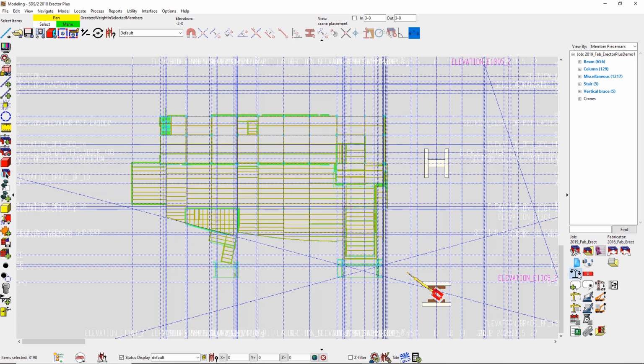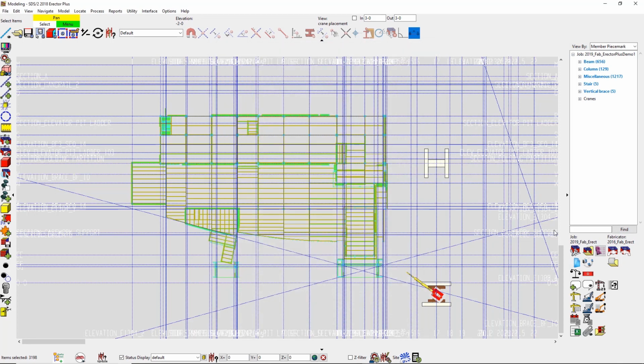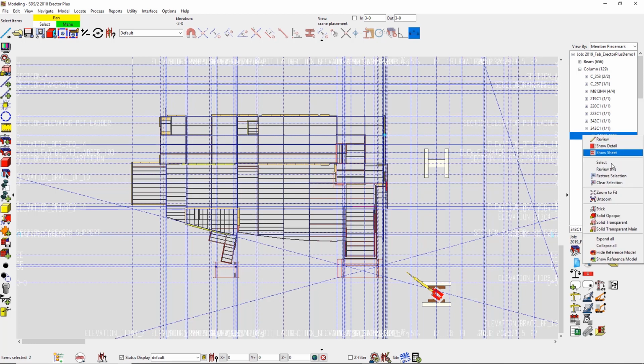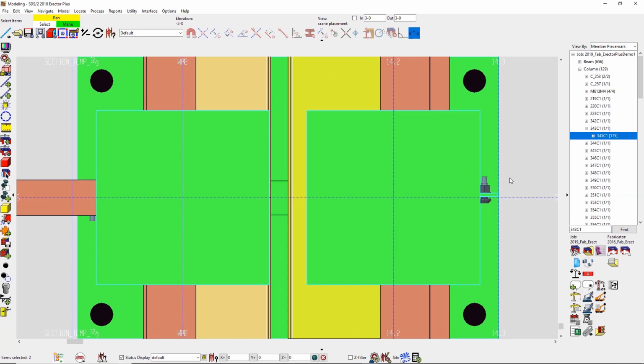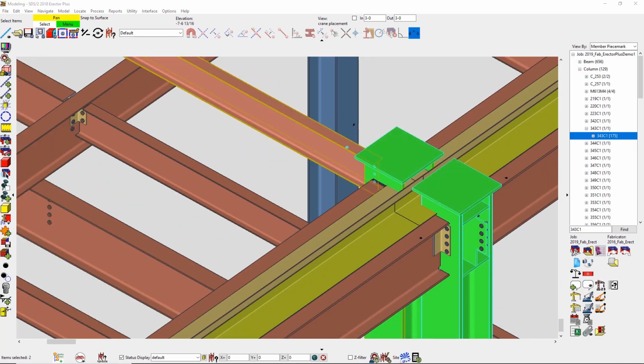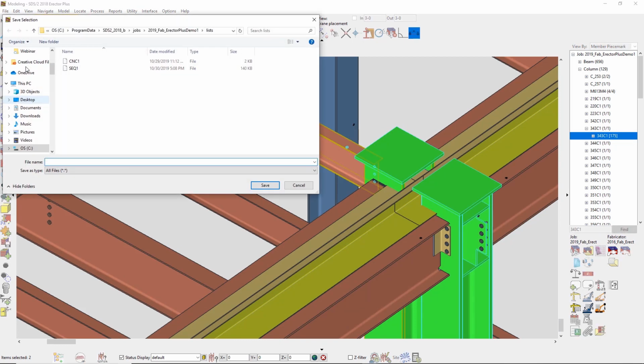So now I want to see what the piece of steel is going to be the heaviest in my fabrication model to see if the cranes are in the correct placement. I can always move them just like before as well. It looks like the piece ended up being correct and they just ended up combining two columns as one. I just want to save this as the heaviest member again for later use in my second webinar.